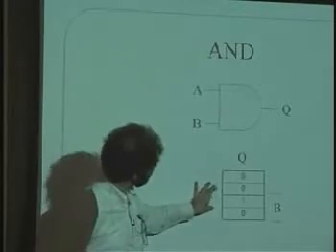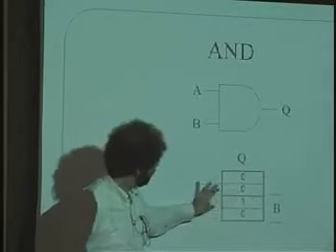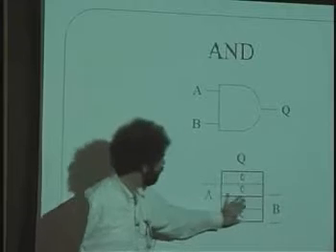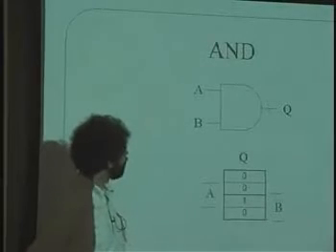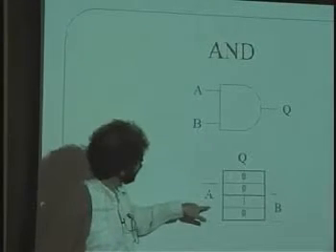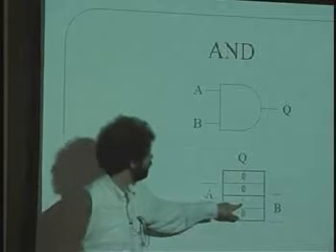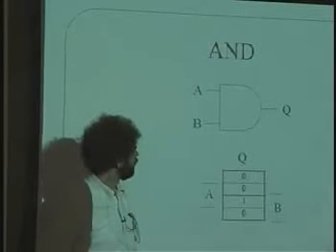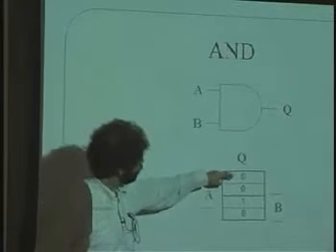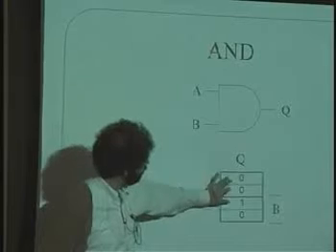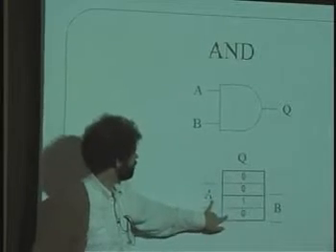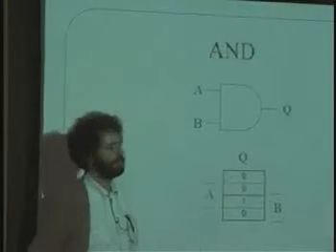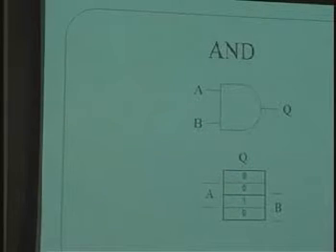So here's where A is true here in the middle. And here's where B is true over here at the bottom end. And you see that an AND is nothing more than if A is true and B is true, then the output is 1. So again, it's a gray code. Both are low, one's high, the other one's high, and then the first one is low, and then going back to both of them being low. So that's the description of an AND gate in K-map form.